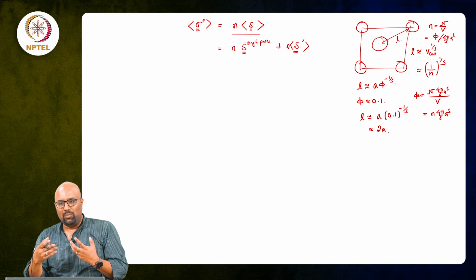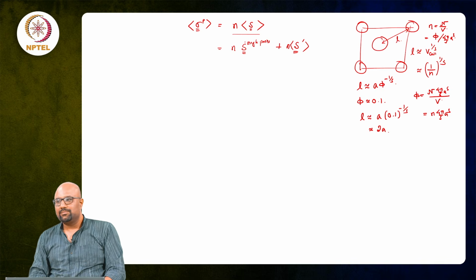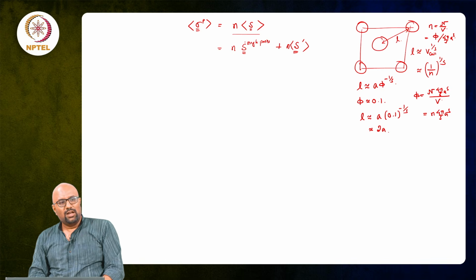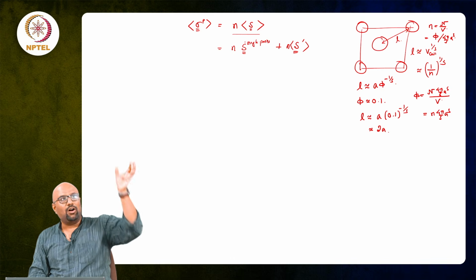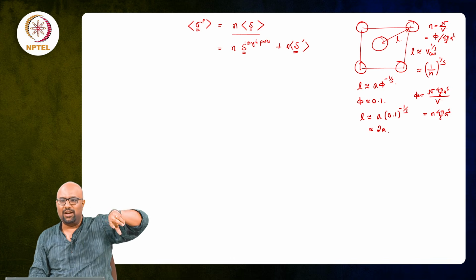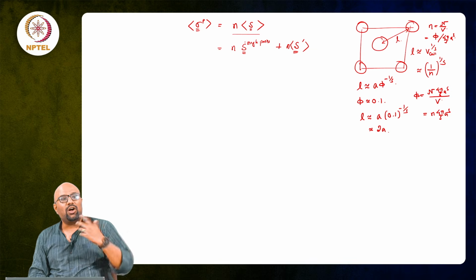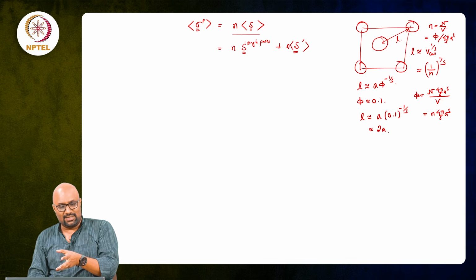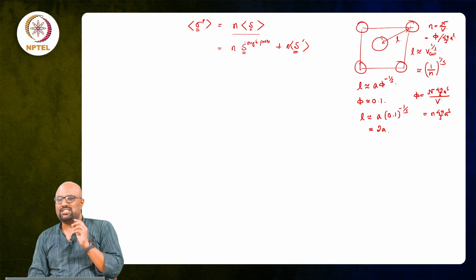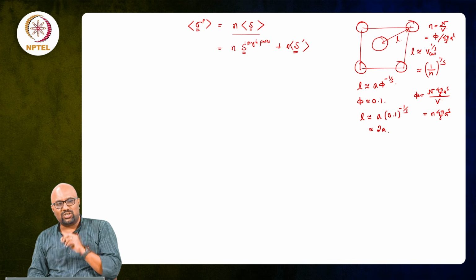That means they are almost coming close to touching, right. So, at a volume fraction of 10%, you will have significant influence of all the neighboring particles' velocity fields on each other. You cannot ignore interaction. So, the exercise here is basically trying to tell you that when you say volume fraction is 10%, that means interactions are important. You cannot ignore interactions.